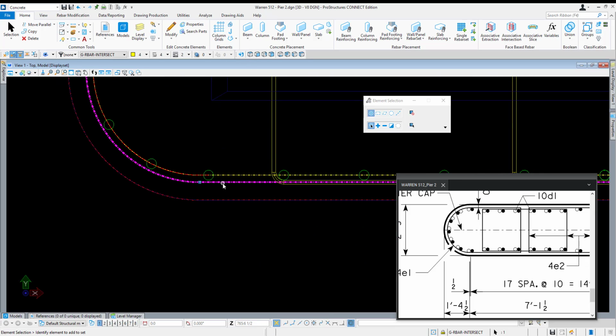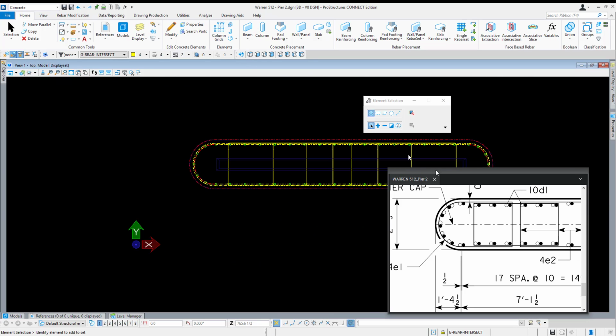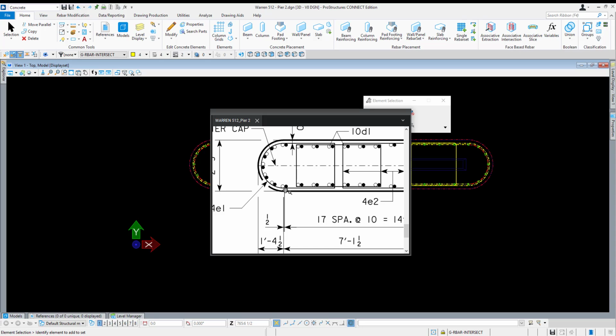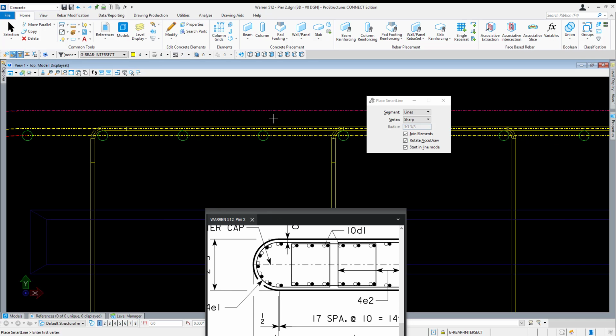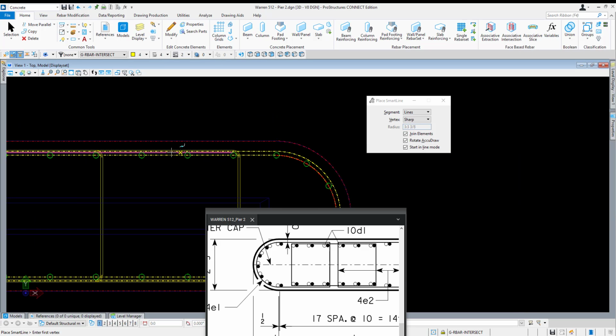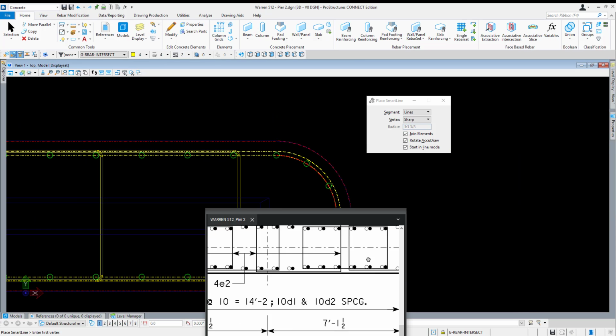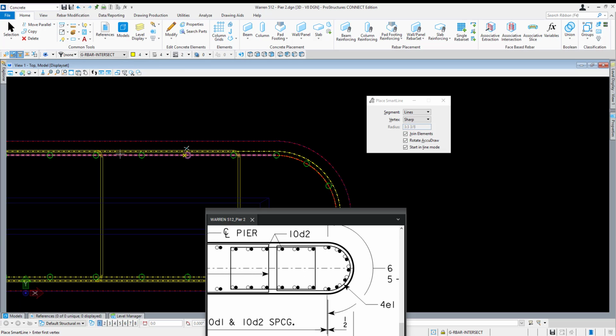So rotate to the top, and let's see what we need to do for our ties. So our ties, we just need the 2 ends, and they need to wrap around 3 of the bars that the column inserted. So this one will have to stop somewhere around here, and this one will come over and wrap around 3 as well, so right about here.